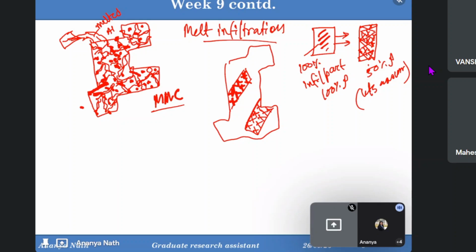You can just see how much wetting is taking place after the process is done by SEM and EBSD, and according to that you can optimize the reinforcement particle distribution inside the mold, because you have to place the reinforcement particle inside the mold. You can optimize the pouring time and the pouring velocity, the speed at which you are pouring the metal, how much temperature you are keeping in the poured metal, how much temperature you are keeping in the mold, and how much cooling you are providing to the mold. This sort of process parameter you can look after. Otherwise, beforehand you cannot determine.